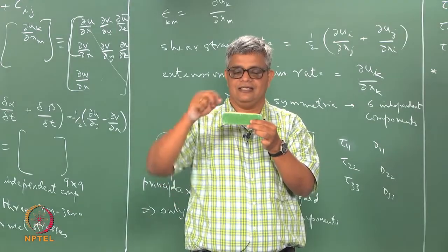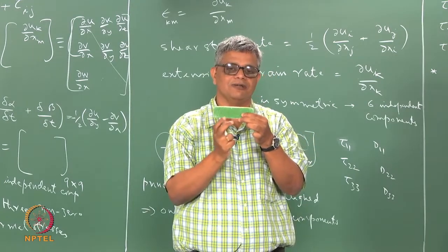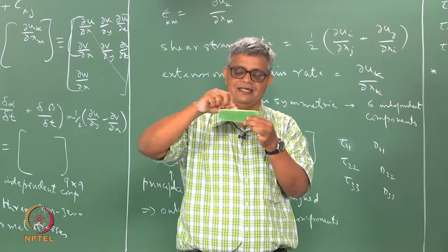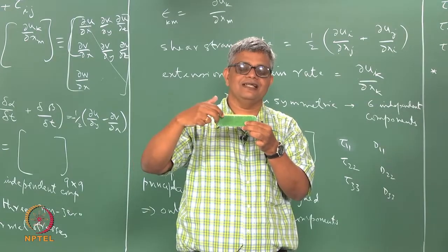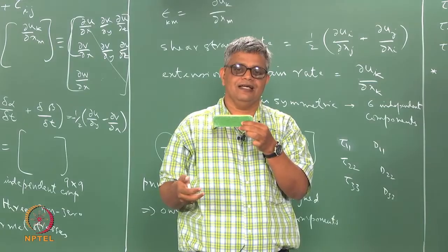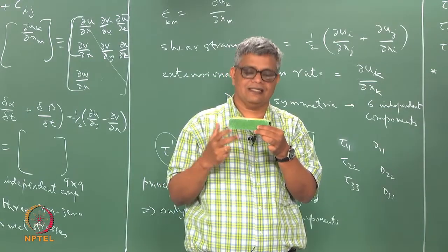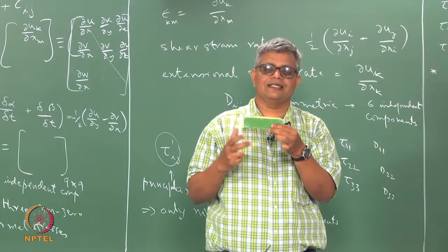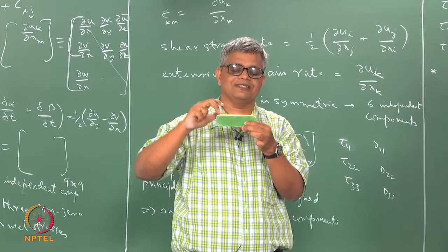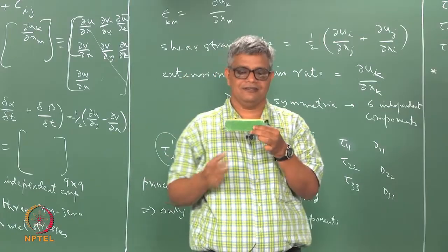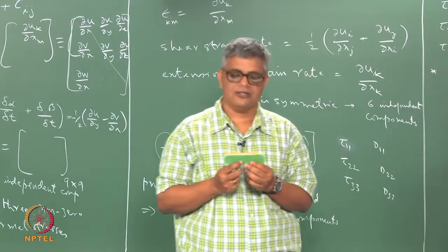Similarly, if you apply in the z direction a certain tensile or compressive stress, and that produces a corresponding deformation in the transverse direction, then the amount of deformation produced must be the same if the same tensile or compressive stress is applied in the other orthogonal direction.